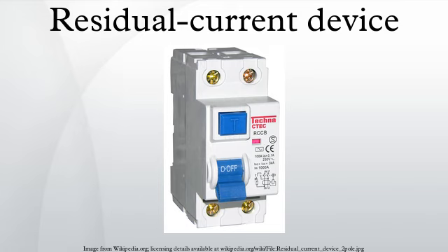Type B, RCD for which tripping is ensured, as for type A, for residual sinusoidal currents up to 1 kHz, for residual sinusoidal currents superposed by a pure direct current, for pulsating direct currents superposed by a pure direct current, for residual currents which may result from rectifying circuits, 3-pulse star connection or 6-pulse bridge connection, 2-pulse bridge connection line-to-line with or without phase angle monitoring, independently of the polarity.